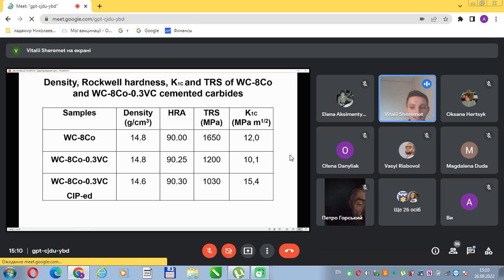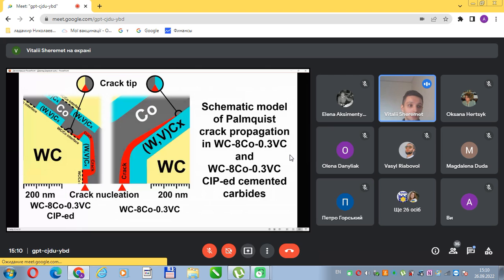As was indicated, cemented carbides with vanadium carbide grain growth inhibitor additive have almost 3 times lower fraction of the tungsten carbide cobalt interface coherency than that for the alloy without grain growth inhibitor, due to the presence of a complex ion which is based on tungsten and vanadium.